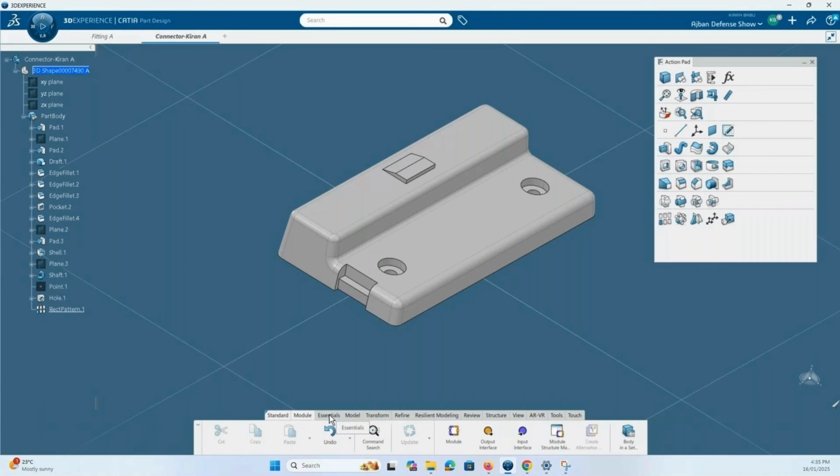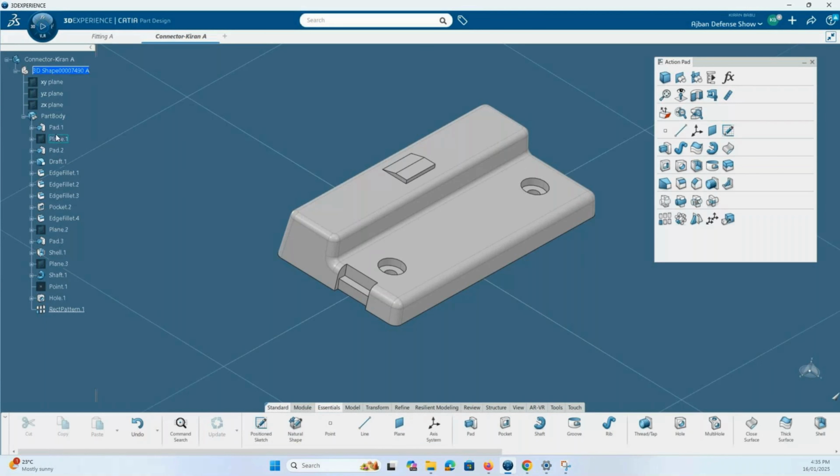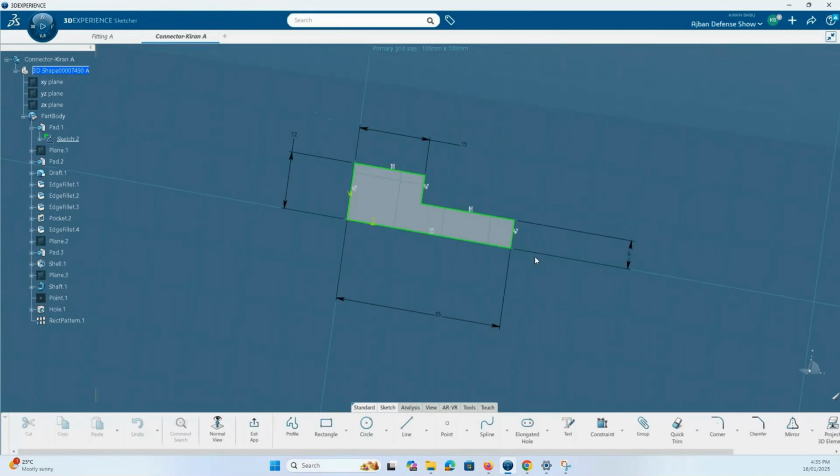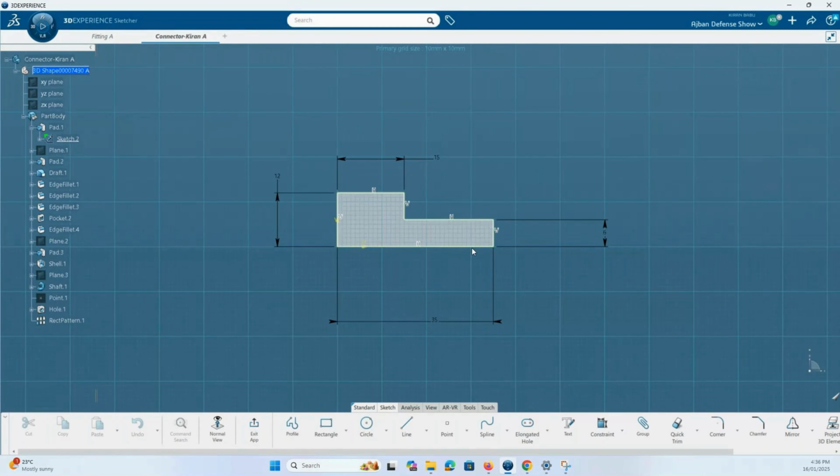So when I start to develop the base model, I have the initial sketch, correct? In the initial sketch, if I'm going to start off building a rectangle, I need to understand what the locking dimensions are. Locking dimensions are base dimensions, which will help me keep the profile intact. Here, the base dimension, if you ask me, would be 35. And on that 35, I'm going to build different dimensions to support that 35 as a base.